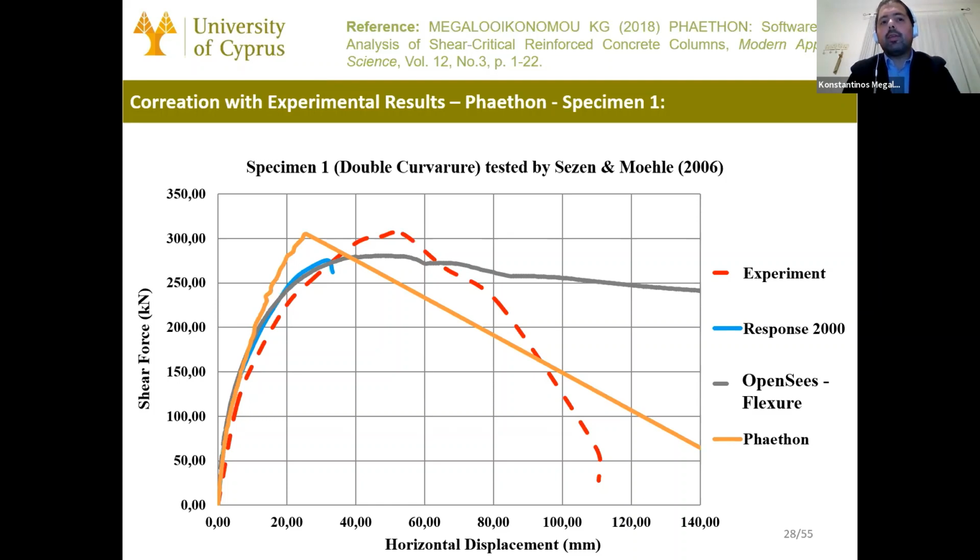Since I was based on this constitutive law, I couldn't capture the post-peak response. But I used a linear connection between the point at shear failure and the point at axial failure, to approximate this part. But the most important advantage that I told you is to capture the contributions of each deformation mechanism at each step of the analysis.